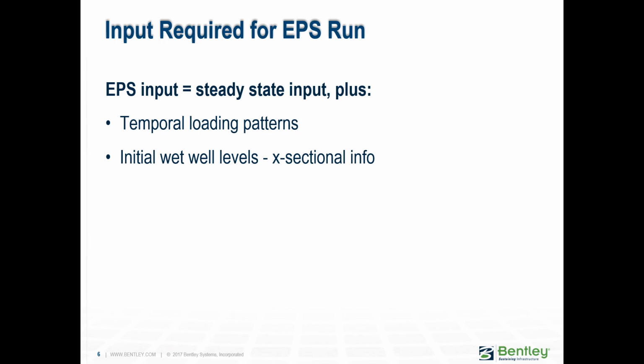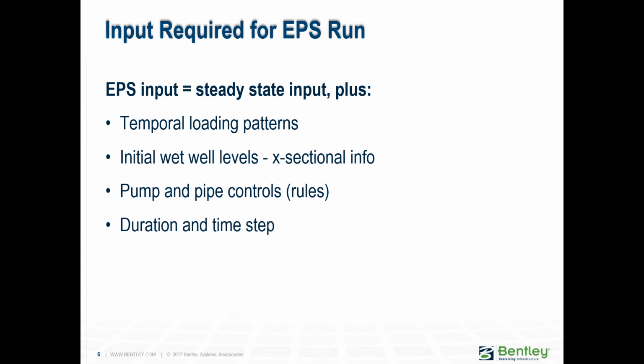Also, we need to know at the beginning of the simulation what was the level inside the wet well and what is the cross section of that, and very precisely, because we need to know how the volume will change. You need to know how your pumps are controlled. So what are the triggers? If there are pipe controls, you need to know that as well. You need to determine how long you're going to run this for. So 24 hours, 48, 72, more. And what is your time step going to be? Typically an hour.